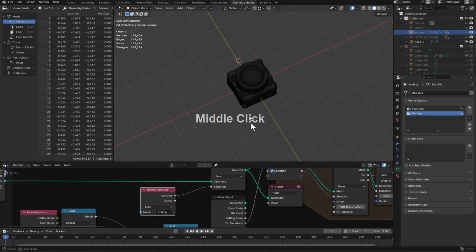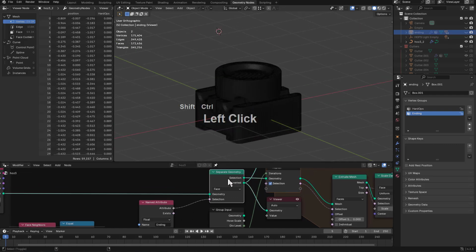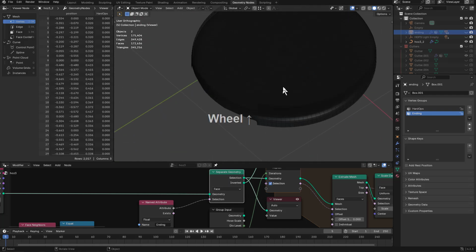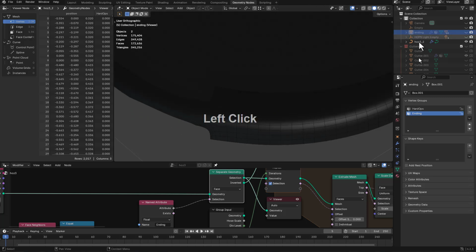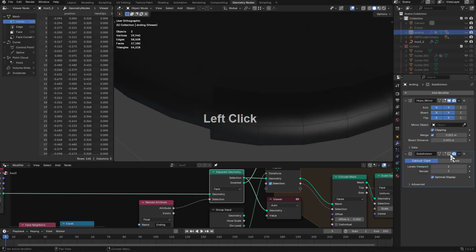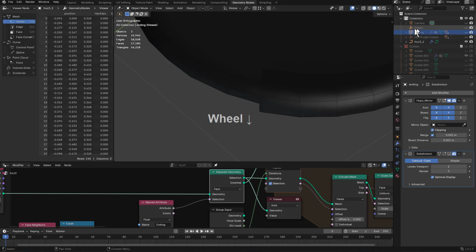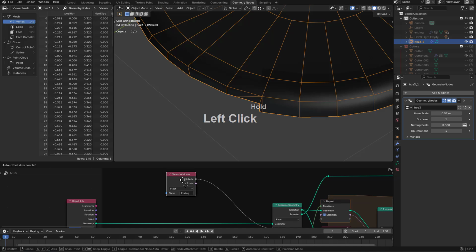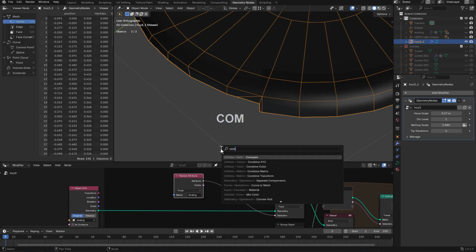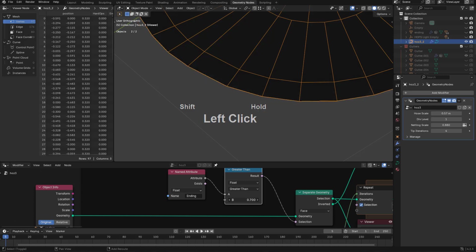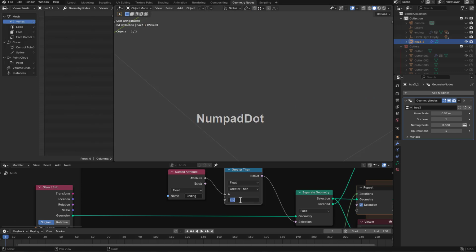Let's connect our attribute. We'll cut our connection just so we look at the first one, and we see that we are getting more of it than we need, and also we're getting more geometry than we need. So let's go to the ending geometry. Let's disable subdivision for that, because we probably give it one in the end. And since our group is grabbing a little more, let's use a compare, and we'll just clamp that maybe to what was it, 0.7?